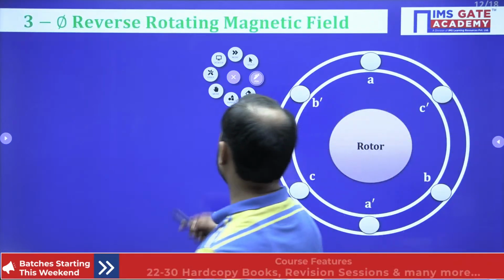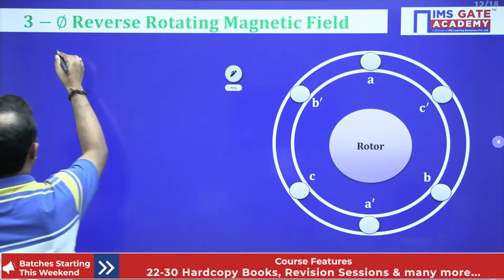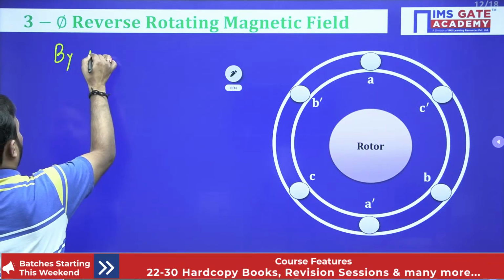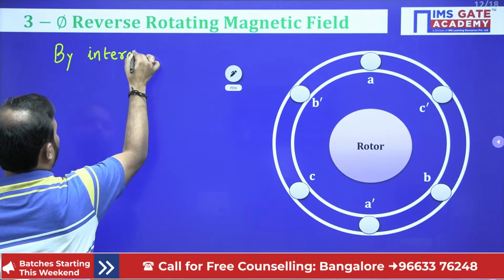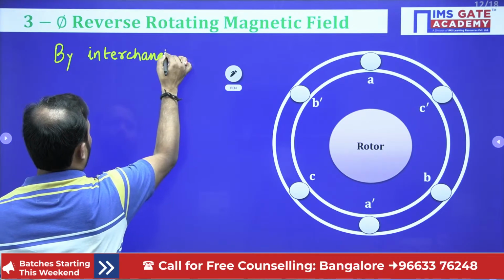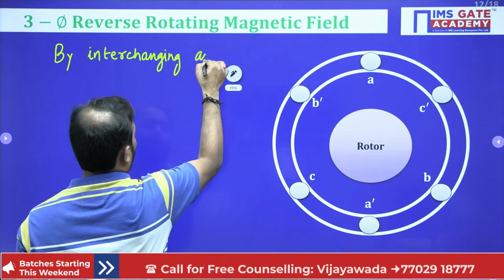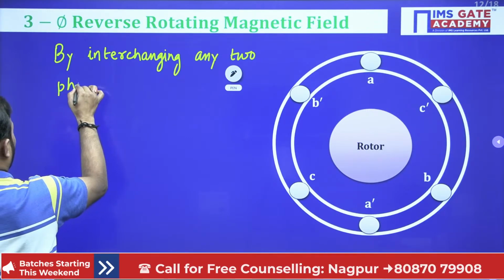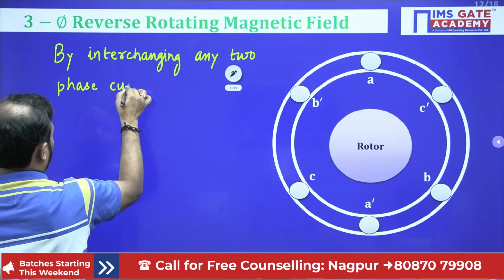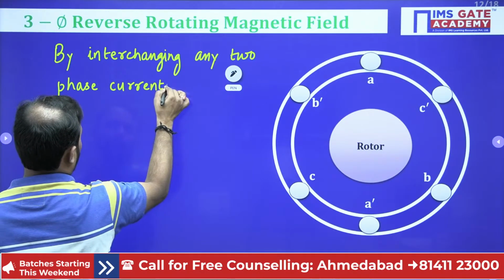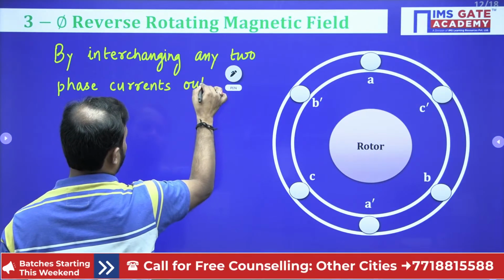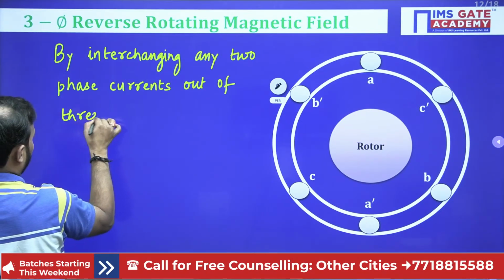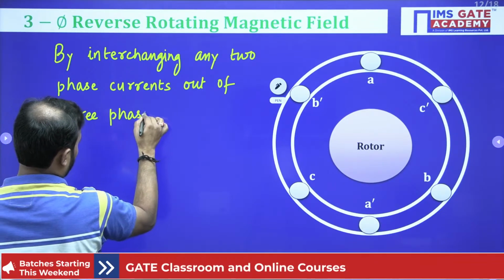It is possible by interchanging any two phase currents out of the three phase currents.